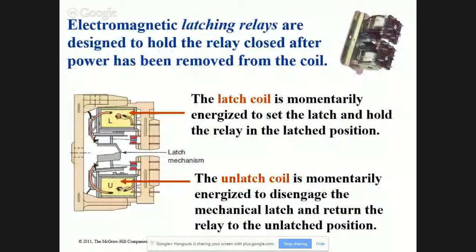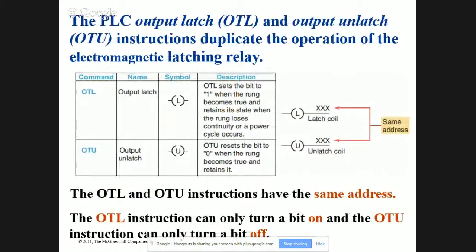Latching relays. Seal-ins. Same thing as latch. Well, we don't have to actually have a seal-in. Before, on an OTE instruction, we've simply been telling it to activate, and it puts a 1 in there. When we don't activate it, when the logic to the left of it becomes false, it goes off. But we have a latch instruction and an unlatch instruction.